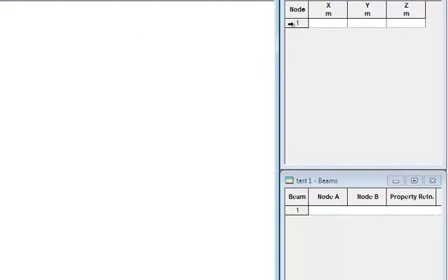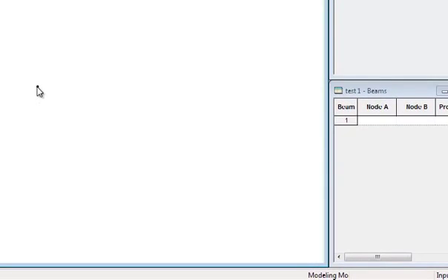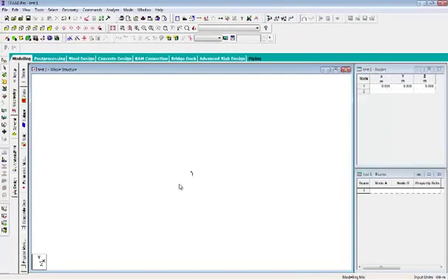Fine. So now this is snap node case, so we will just close it down and create our first node. Let us create it at 0 0 0. Just you can see here the first node. In order to display the node number on the screen, just press Shift plus N. It will display the node number. Just see, 1.